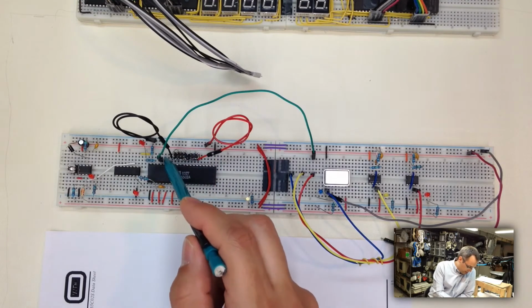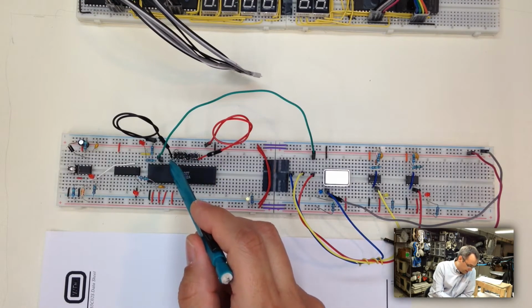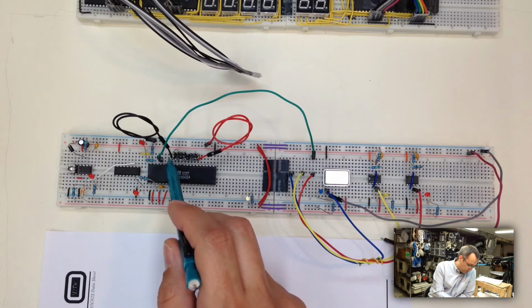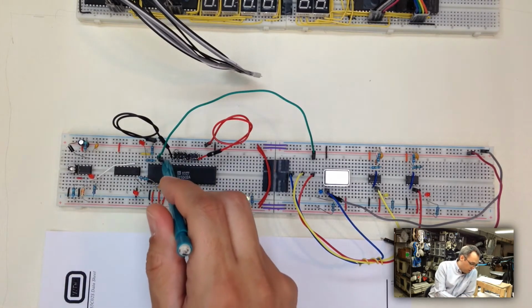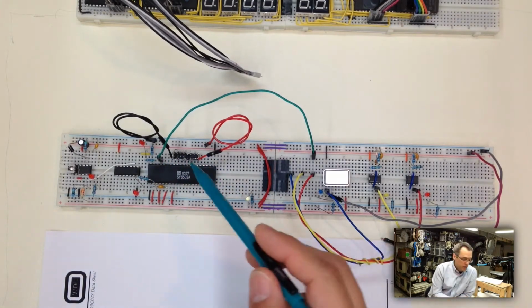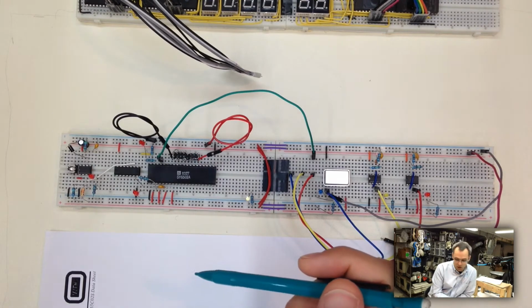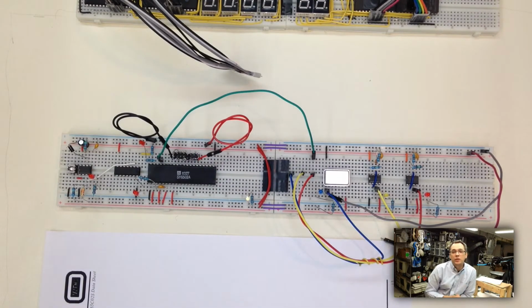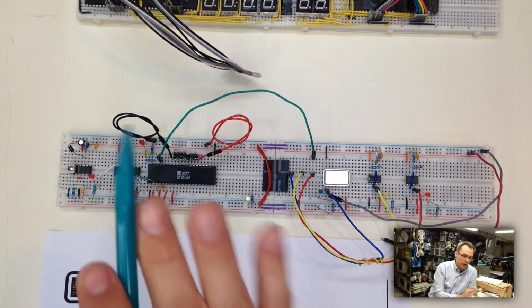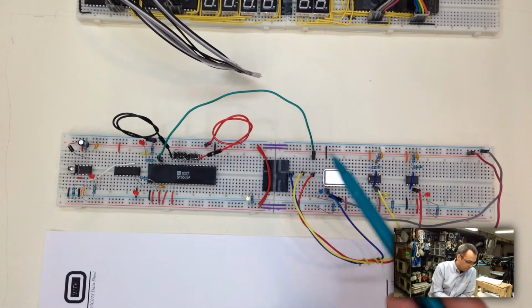There's a few extra pins in here we're not using. Some are not connected. Some are the read-write and all of that stuff. We will be getting to those pins later on. These pins are used to signal to the other bits and pieces of the computer, hey, I'm the CPU and I don't need to be doing anything right now. You can have the bus. So we're going to be coming back to those pins eventually.